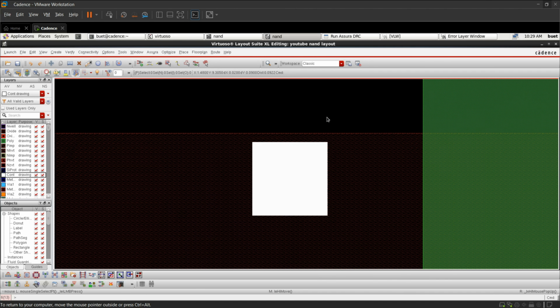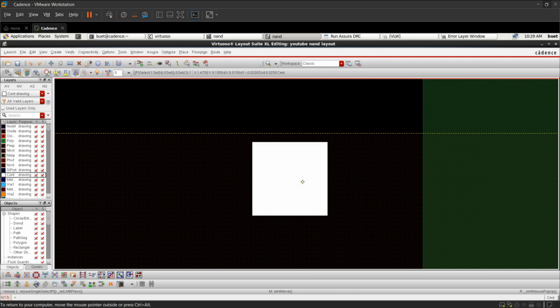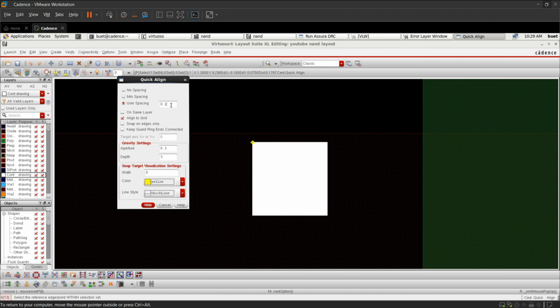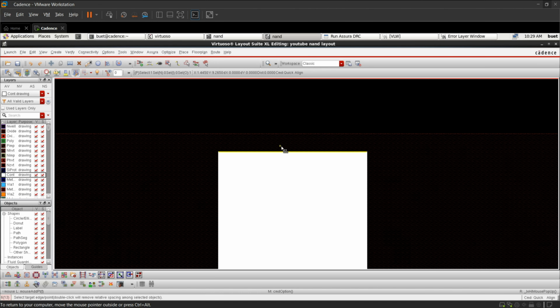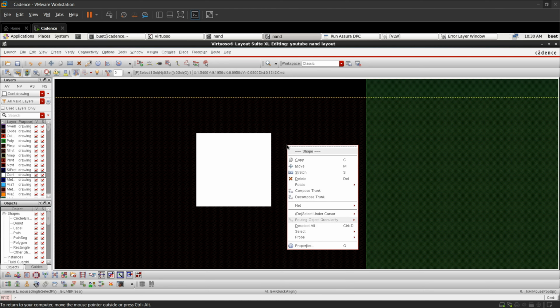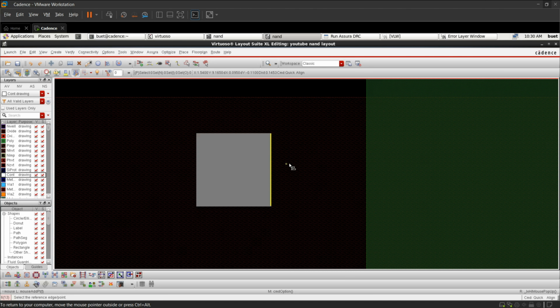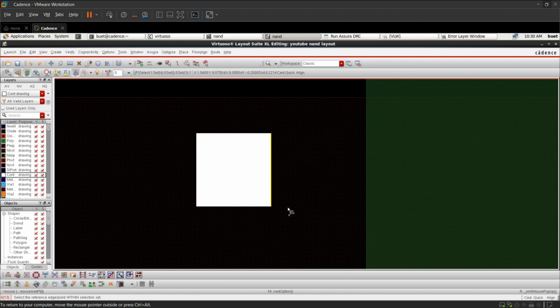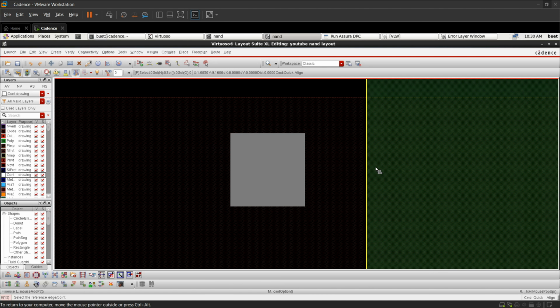As we know, in the last video we have seen the spacing between our oxide edge to this contact edge is 0.06. Select this contact, make it 0.06. On the side, select this edge, it is 0.06 and this spacing should be 0.1. Sorry, press A, options, make it 0.1. On the side, select this entire contact, it is 0.1.